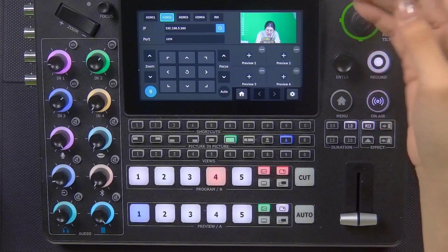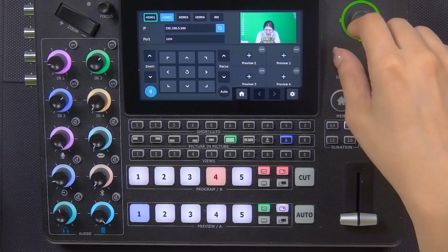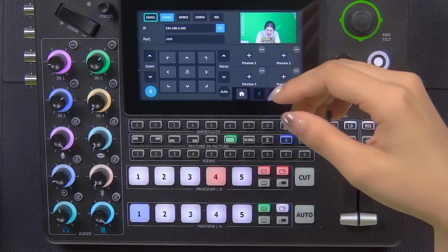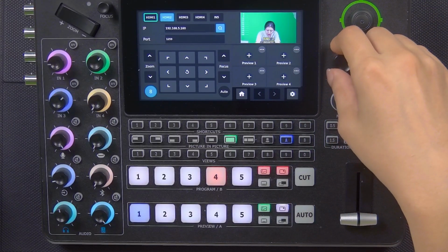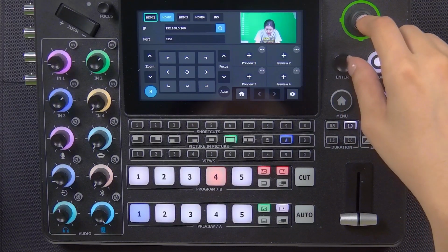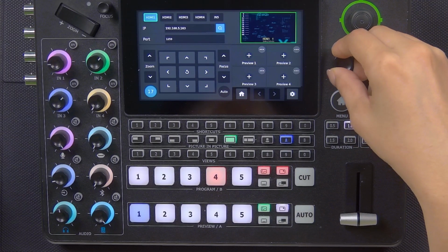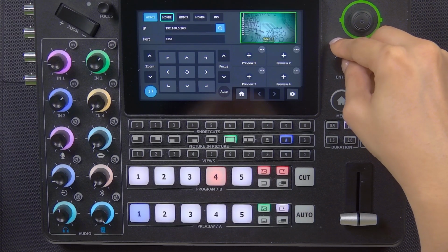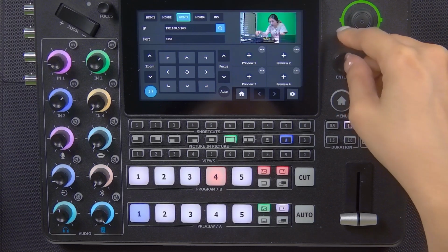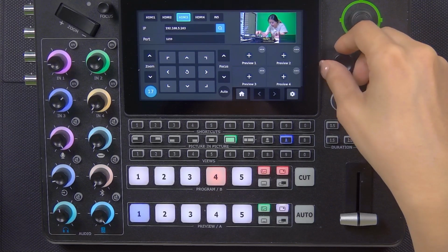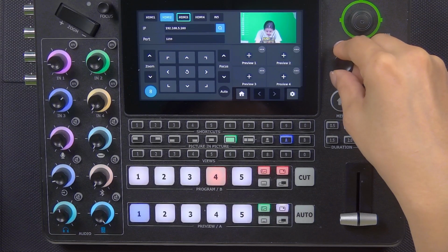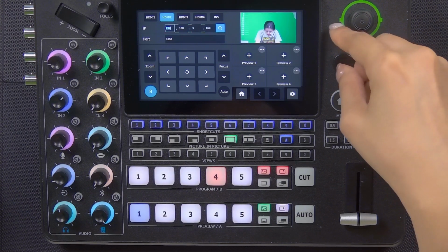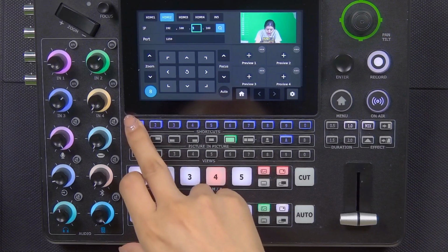We can see from here that we can control a total of 5 PTZ units. 4 of these channels are controlled via the IP VISCA protocol, and I currently have 2 PTZ signals connected, HDMI 2 and HDMI 3. Select the corresponding input signal, and we can manually set the IP address here.